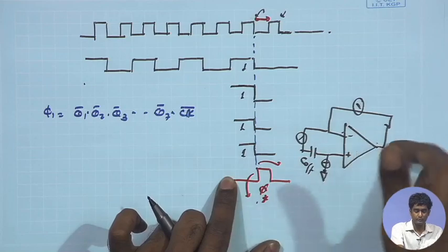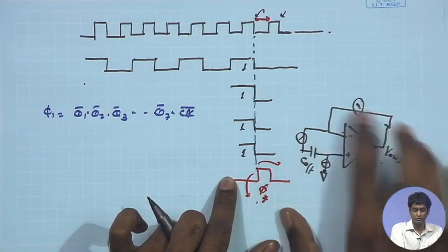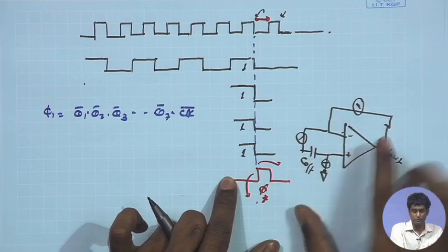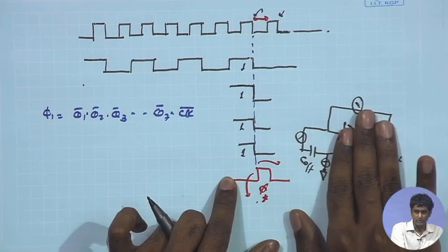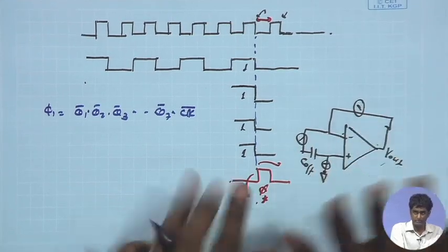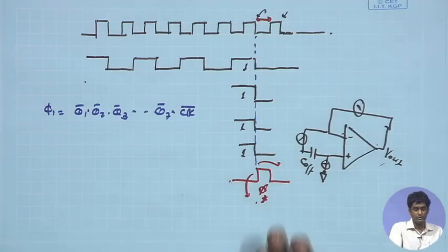but for the closed loop bandwidth we have effectively this large C off coming, that loads the comparator in the closed loop. As a result, you have to use the compensation capacitor, and as a result the bandwidth goes down, and in order to make sure that the bandwidth remains sufficiently high, I would like to stretch this. So, this question is clear.